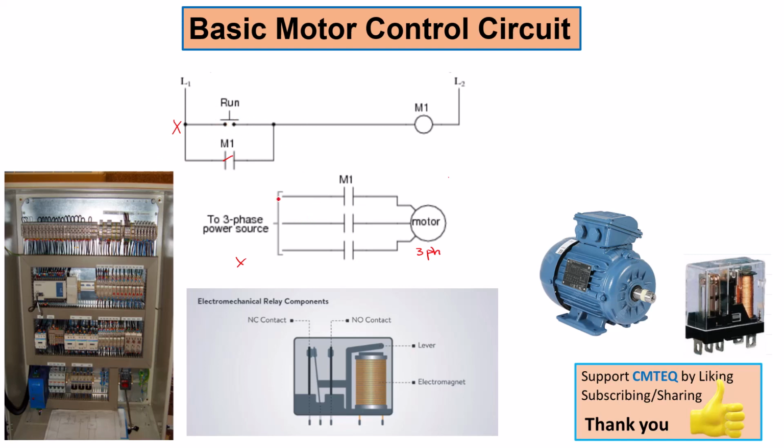Obviously, if you pull the plug, you remove the power, you cut off your L1 and L2, then your motor should be able to stop. But that is dangerous. So you should have a button here that should cause this motor to stop. Now, where do you include your button? Do you insert your button here? Or do you insert your button here? Where do you put your button so that you can deactivate or disconnect this latch circuit from taking power into your motor?